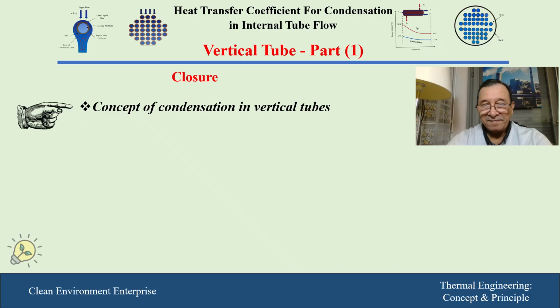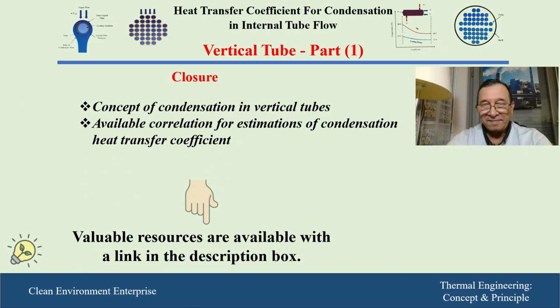And at the entrance of the tube from the above side, we have also single phase vapor. And we may use convection heat transfer coefficient correlations for that. And these correlations have been described in our previous episodes when we talked about convection heat transfer. And then we mentioned some of the available correlations and how to predict the heat transfer coefficient for condensation.